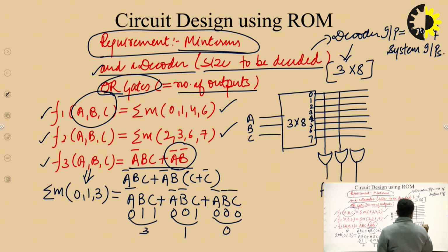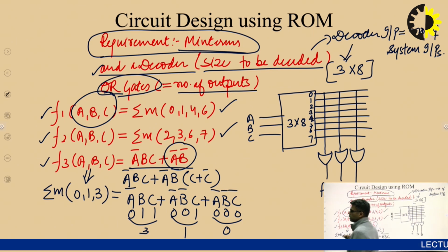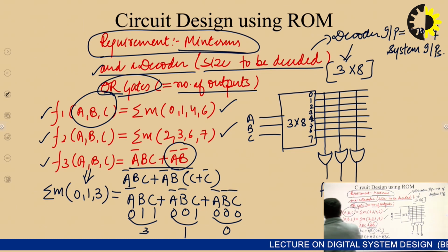Simply draw a vertical line which is crossing the decoder outputs. So there is a matrix available to me now at the output section which can be used to program as per my requirements. So let's program this ROM.